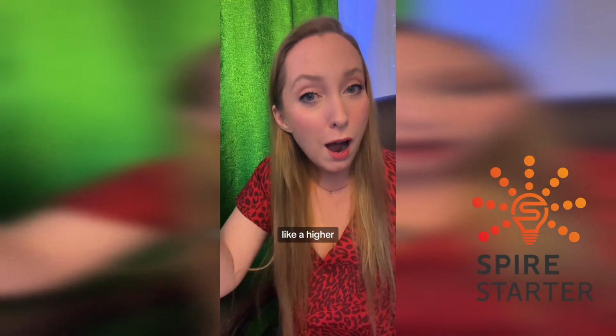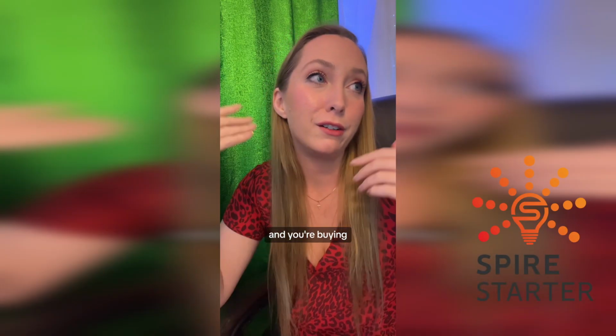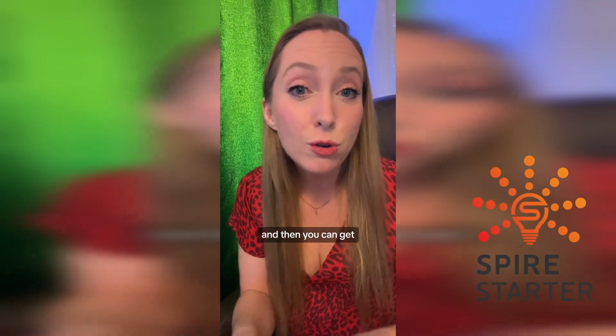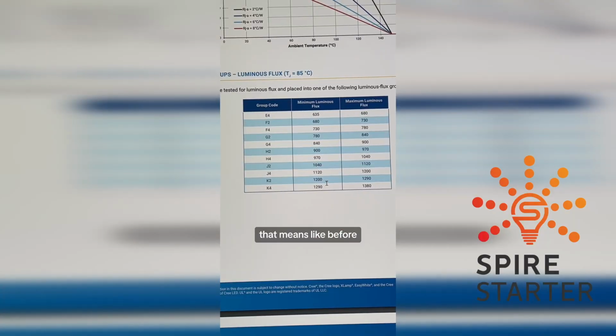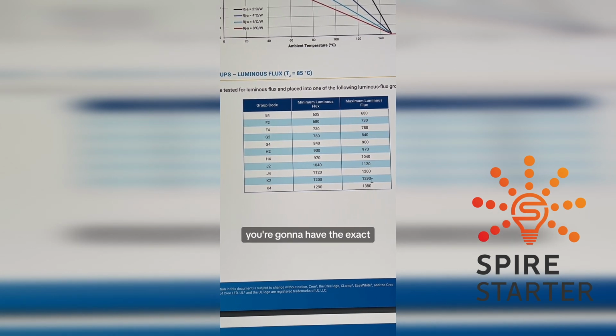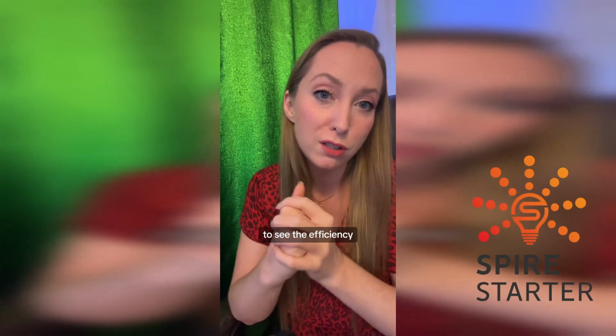But if you're a higher level manufacturer that makes luminaires all day long and you're buying hundreds of millions of LEDs from different vendors, usually you have a good relationship with that vendor, and then you can get characterized LEDs. That means, like before with the 1250 lumen LED that we used as an example, before you'd only know that it was in a K2 flux bin between 1200 and 1290. But if you get characterized LEDs, you're going to have the exact manufacturing measurement that tells you it's 1250. So it's much more exact. And then with that, optical engineers can back calculate to see the efficiency of the whole system.